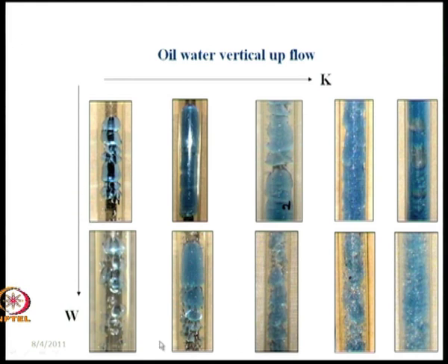Here also we have tried to do it at a higher water velocity. Here we find that the kerosene droplets are smaller, and in this case water is very finely dispersed in kerosene. It is sort of an emulsified flow. This is something very special for liquid cases. There are certain other interesting factors for liquid cases which we will be taking up tomorrow, and then we will go to some other unique features of flow patterns for different geometries and different flow conditions, and so on.